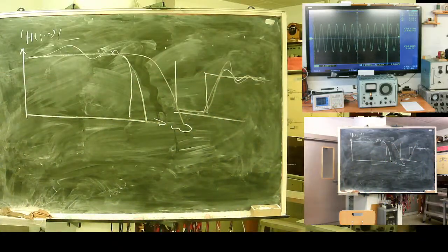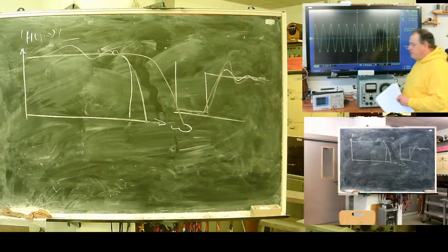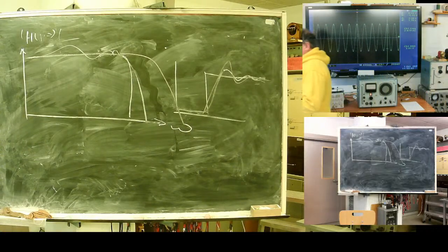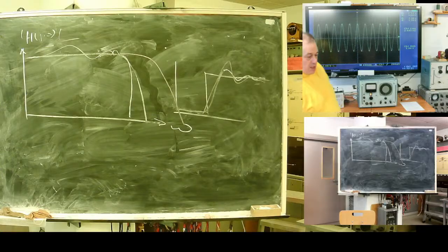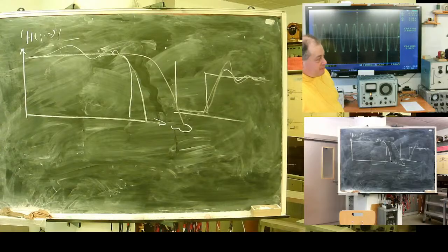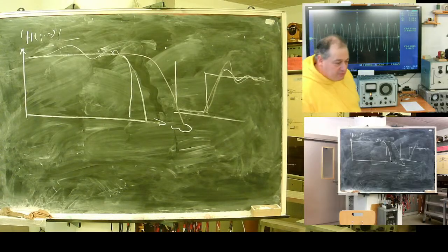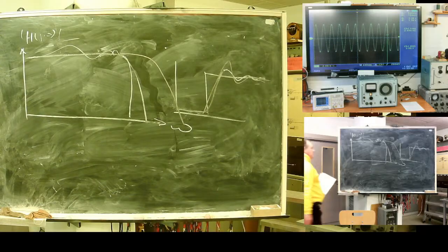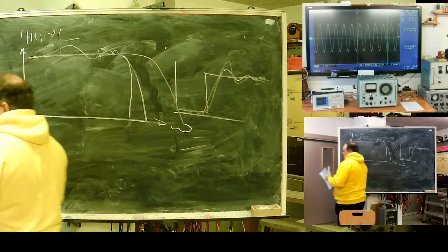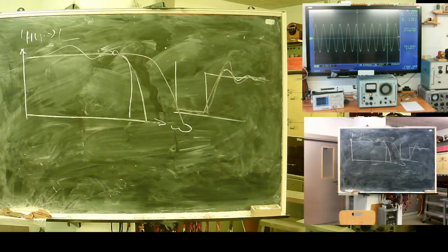High rank Chebyshev filters are performing nicely on transients. If you need to deal with transients, your best solution is a Bessel filter. Bessel polynomials can be used to create a very good filter. But here at cutoff, Bessel filter isn't the best.